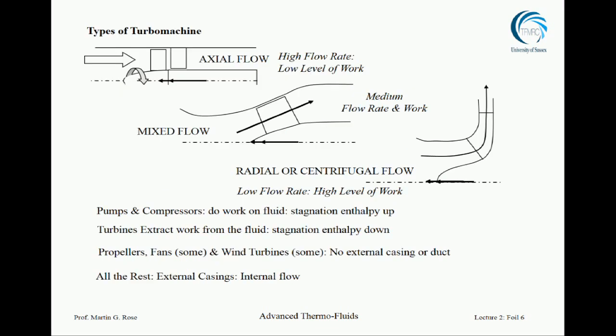Some basic terms being defined. When we're talking about turbomachinery, you'll find I immediately use the terms axial, centrifugal, or mixed. And these are geometrical statements. The figure in the top left here is an axial flow machine. It happens to be a pump, the way I've drawn it. The flow is along the axis, and the aerofoils hang radially. One is a rotor, the other is a stator.